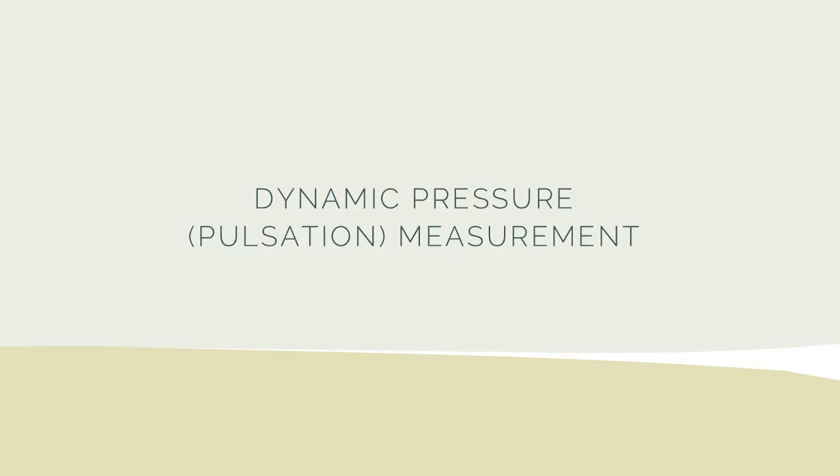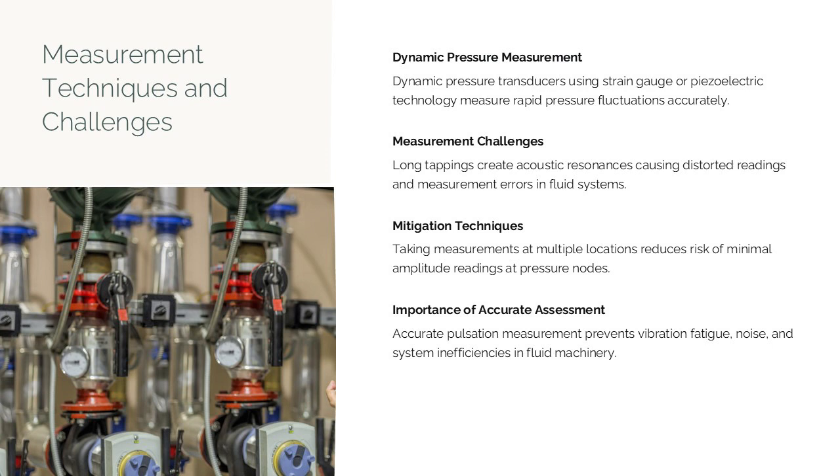Measurement techniques and challenges. Dynamic pressure measurement, or pulsation analysis, is essential for evaluating pressure fluctuations in fluid systems, such as those involving compressors and pumps. Standard static pressure transducers lack the response speed needed for accurate pulsation measurements, especially at higher frequencies. Instead, dynamic pressure transducers based on strain gauge or piezoelectric technology are used, offering wide frequency bandwidth capabilities.